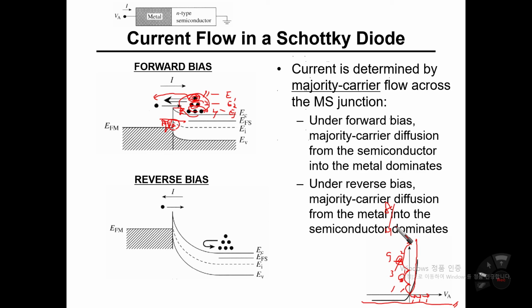All right. What about the reverse biased one? As shown in this plot, even though the negative bias has been increased linearly, the total amount of current flow across the Schottky diode is constant and very small as compared against the current flow when the diode is forward biased. Why is that? Why can a constant current flow?